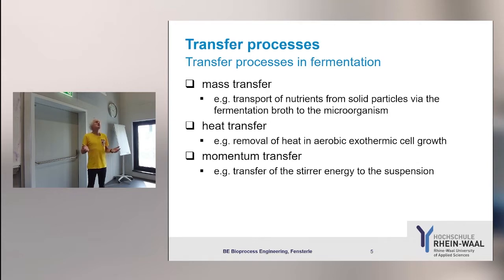But in general, if you dimension a reactor, you have your cooler there. So you would not dimension it just for a very simple process. You will say, my cooler is dimensioned in a way that all regular processes I can think of for this reactor will work. So it's not a good idea to dimension equipment so that it's just enough for your process. Then you come up with another process and you realize the cooling power is not enough, because then you have to buy another one.